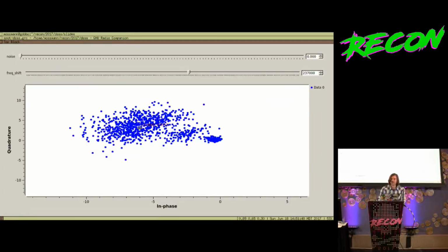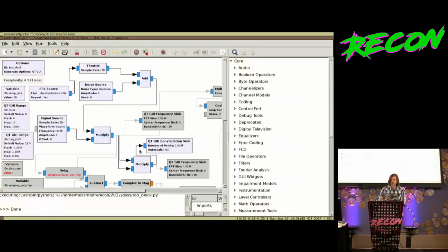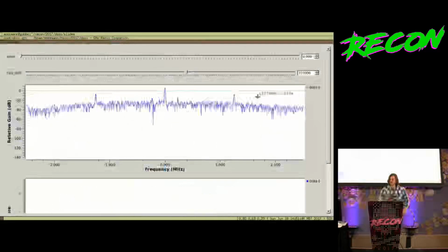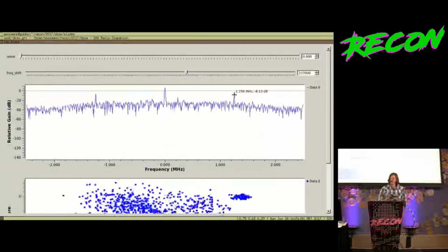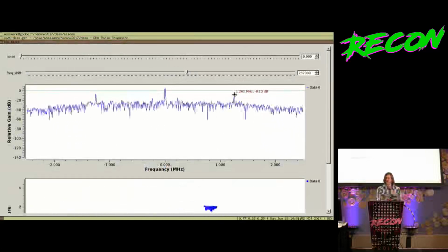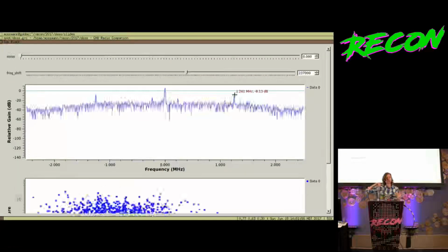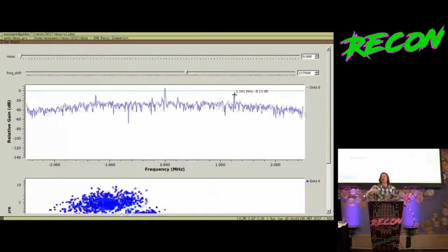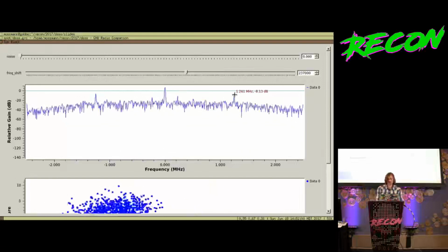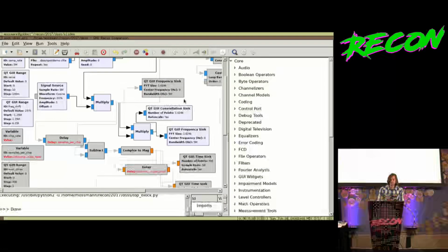And that's exactly why we get a peak right here at 1.25 megahertz, because it's picking up the fact that we're swinging to the origin and back 1.25 million times per second. So now we know the chip rate. I can plug that in over here.